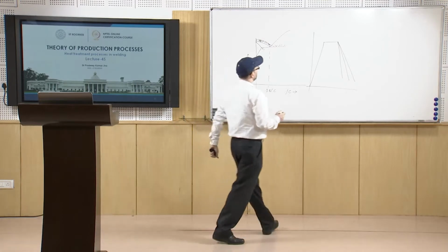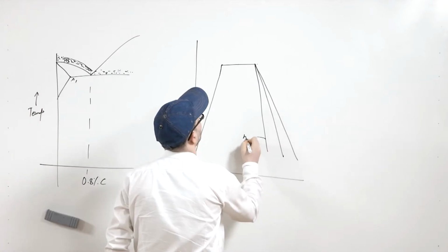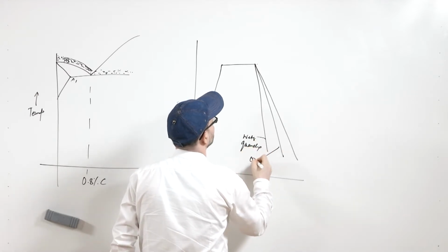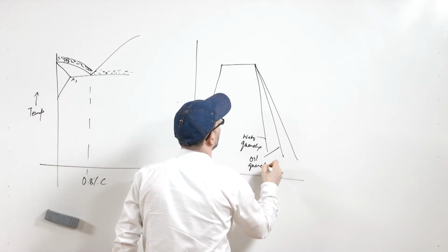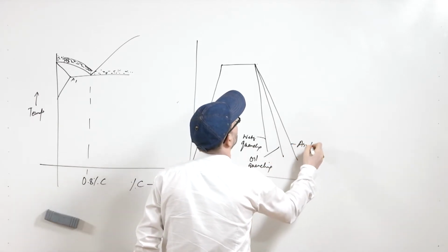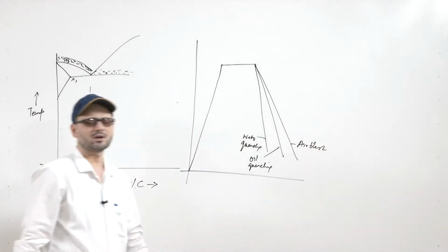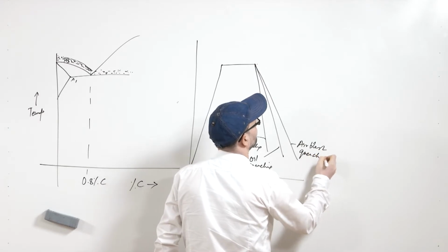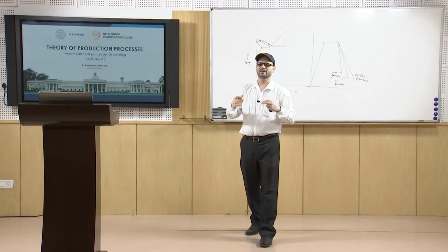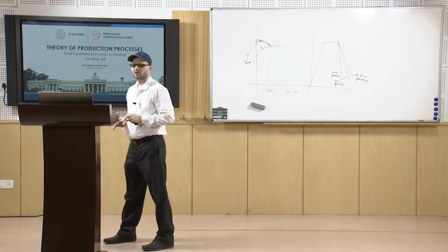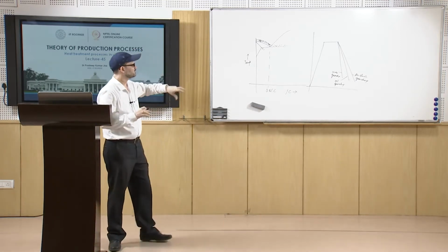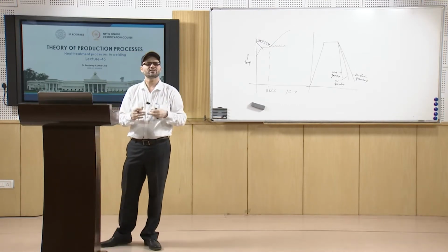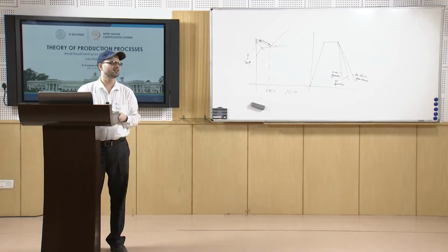This will be very fast. So you will have water quenching, then oil quenching, and this may be by air blast. When we talk about normalizing, it is done in free air. We do not have forced application of air, but once we have forced application of air, it is known as quenching again, because the heat extraction rate will be quite high. That is normally done in the case of quenching.